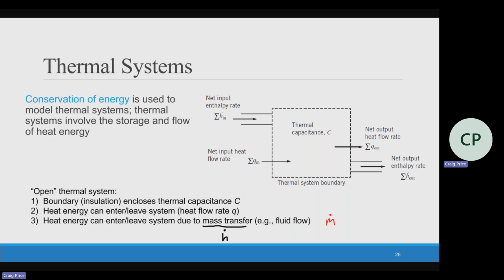And so we are increasing the temperature of our capacitance based on that different flow. And so our equation handles both of these. This is related to some kind of mass flowing in. If there's no mass flowing in, it's just purely based on Q. What's my input heat? What are my output heat flows?